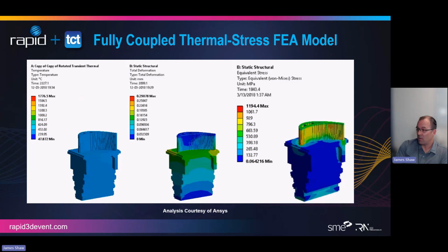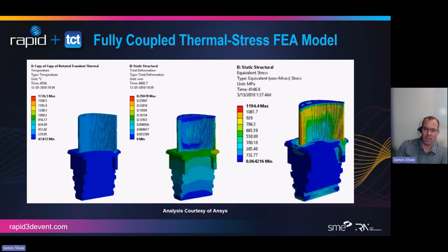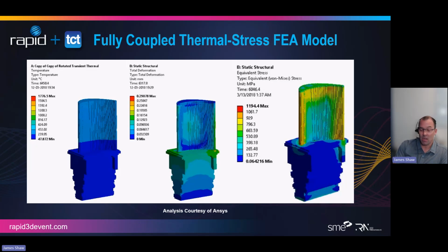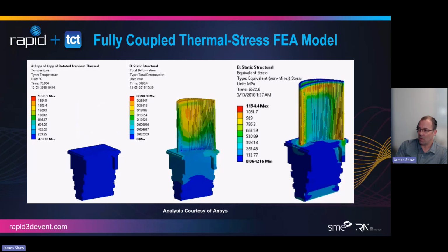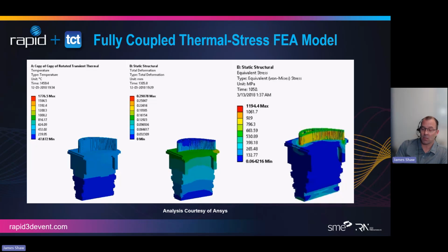We have some sort of a blade here, right? Some turbine blade. And one of the challenges with turbine blades is you start off with a big hunk of metal and you have to remove at least half of it. You've got all these chips on the floor. We've developed these incredibly automated 5, 6, whatever axis machines to try to create this amazing shape, this optimized turbine. But additive is a really, really, really good solution here, because we can get really close to that net shape, and then all we have to do is go back and maybe do a single pass or a double pass on a CNC to get the surface finish we need for fatigue.